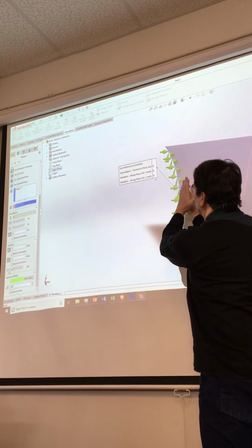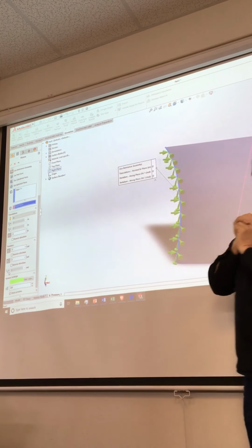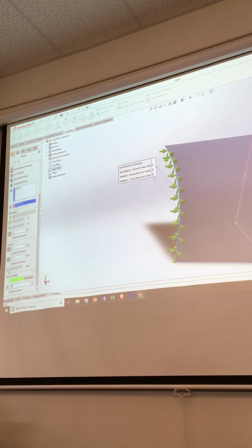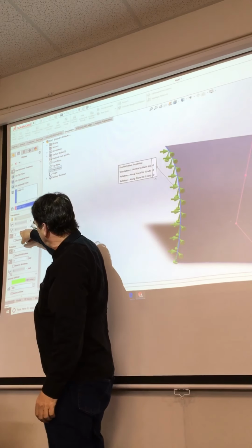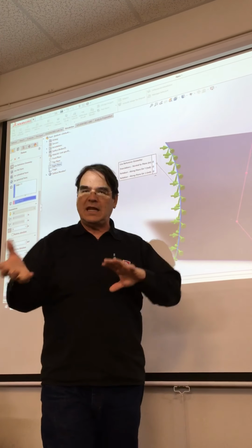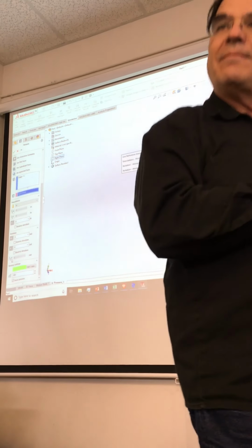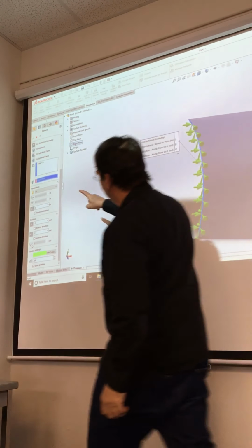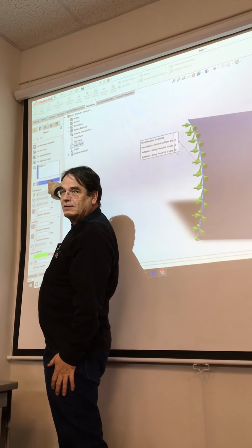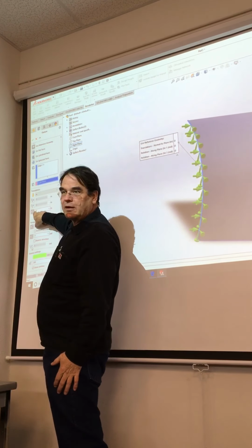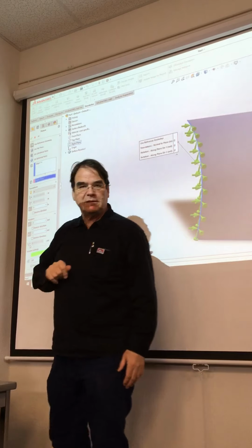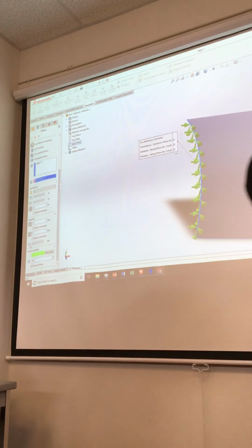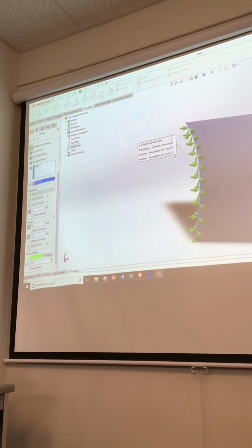We've got this plane here, it can't bend this way, right? Can't have those out of planes bending. That's called a symmetrical boundary condition. What we have done is we've fixed the out of plane translations and we fixed the out of plane rotations, okay? And the way they're described is if we pick our definition plane correctly, we fix the out of plane translation and then the opposite rotations. Okay? So that plane can rotate